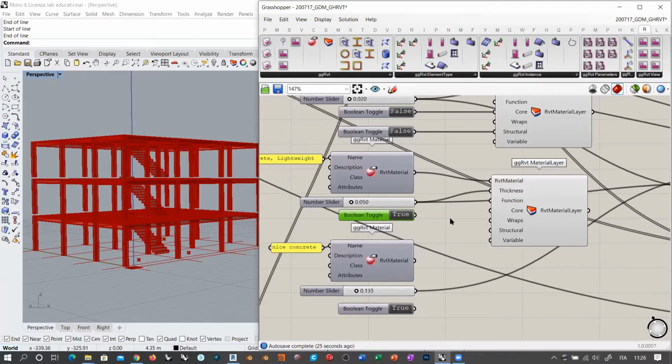So the way you define the core has several consequences in Revit. Probably from the architectural point of view, the most relevant is the way that finishes and core layers are connected. For example, when you connect a floor with a wall, the layers behave automatically according to whether they belong to the core or not. So there are several considerations that you should make eventually for this.